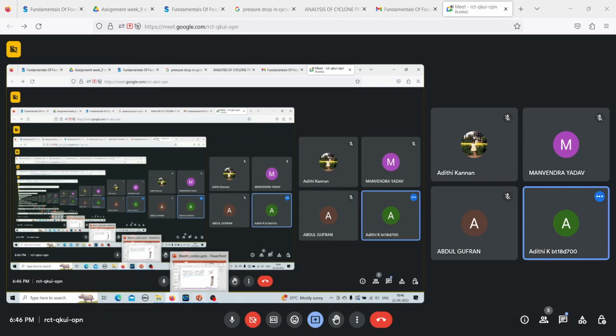inside the pressure equation. And omega is not given in RPM, it is actually radians per second. So you convert this into 2 pi into n, where n is given in revolutions per second. From there you can get the pressure. So always when you are looking at omega, please do not substitute in RPM, convert it into 2 pi n and then substitute the n value in RPS.